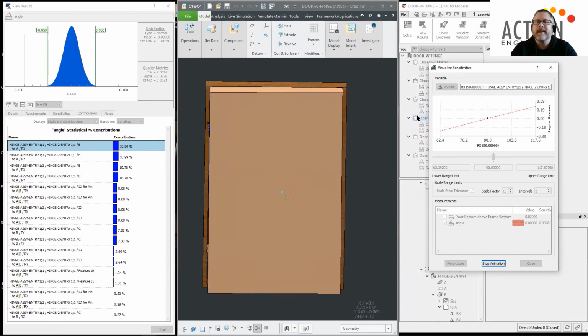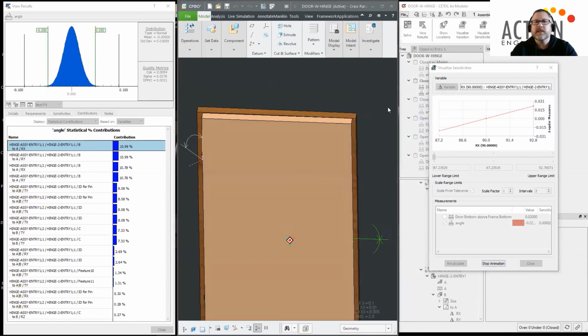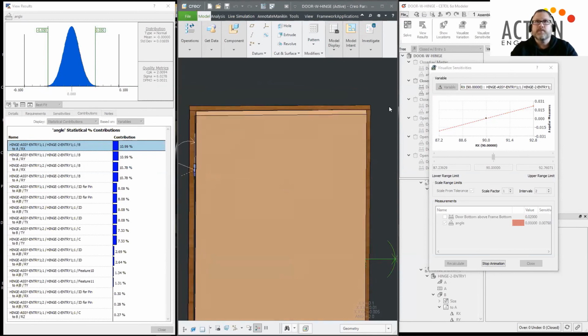But when you're working in, and I came from an electronics company where you're making quantities, high volume manufacturing in the billions. My background was a plastics engineer, a molding engineer. If I could just get an extra 5 to 10% allowable variability in my manufacturing process, spread out across billions of individual components, that is a very significant benefit for me as a manufacturing engineer. My tooling's going to be maybe slightly cheaper. I mean, the difference of going a couple microns can really equate to a lot of value.